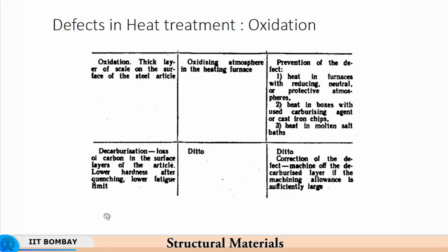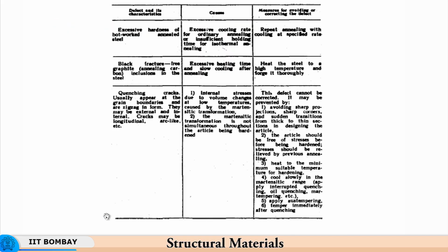Decarburization is also the outcome of the presence of moisture. In fact, even very small quantities of moisture, for instance, even if you have 9 purity gas, meaning 99.999% pure gas, still it might have a certain amount of moisture, which might lead to a small amount of decarburization or at least some reaction at the surface between moisture and the metal.